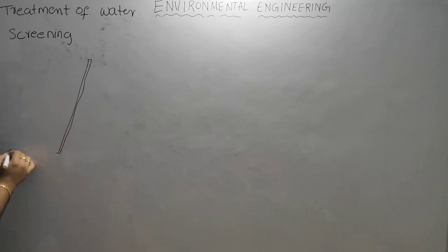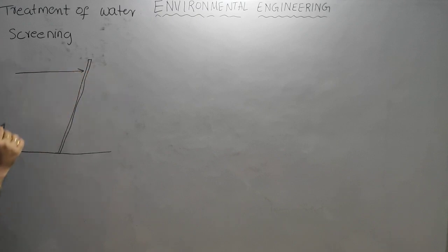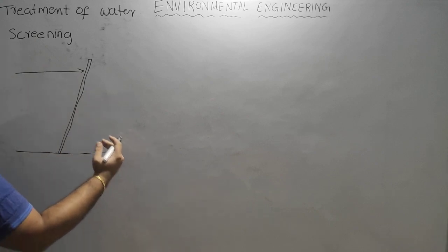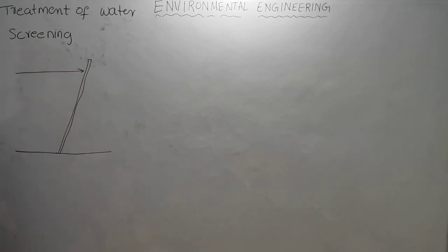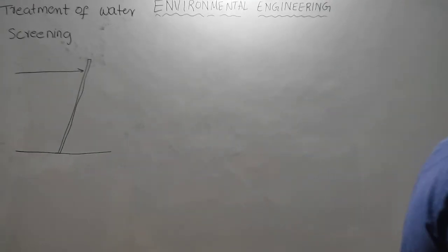then whatever water is coming onto the screen will recede. It acts like a sedimentation tank also. If you keep the inclination opposite to the flow, then it will increase the flow. It is attacking mode. If you keep the inclination in the direction of the flow, then it is accepting mode. Okay. So that is why generally we keep it inclined.